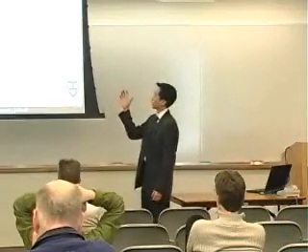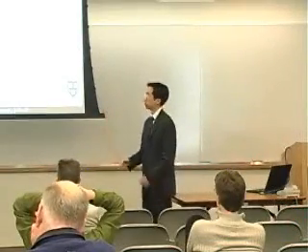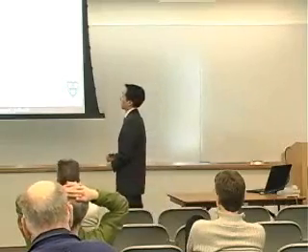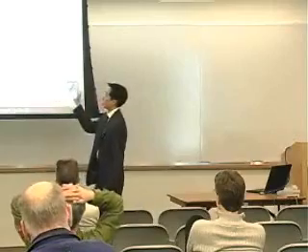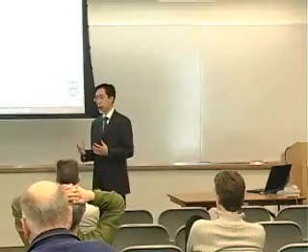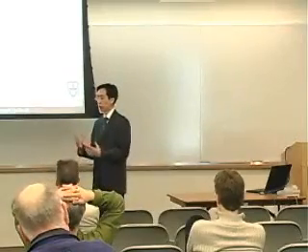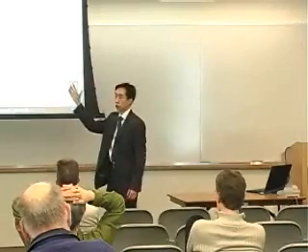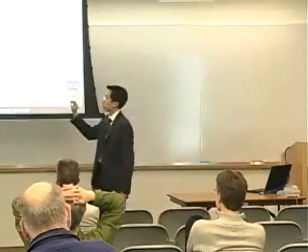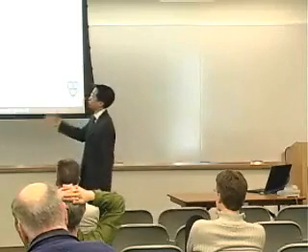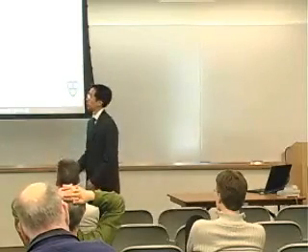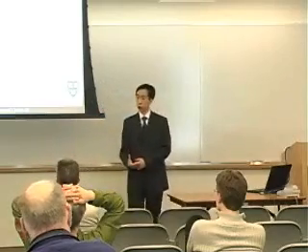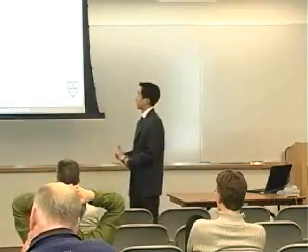So for this work, we'll be looking at a particular benchmark, MCF, from the SPEC suite, and we'll be looking at the bips per watt metric. And if we want two-dimensional contour maps, there are p-choose-2 ways to generate these contour maps for a p-dimensional design space. And we're going to very quickly generate all of those p-choose-2 contour maps using our regression equations, and then rank them after we've computed our roughness metrics. And we'll show that the roughness metrics do indeed corroborate what we observe visually in the design space.